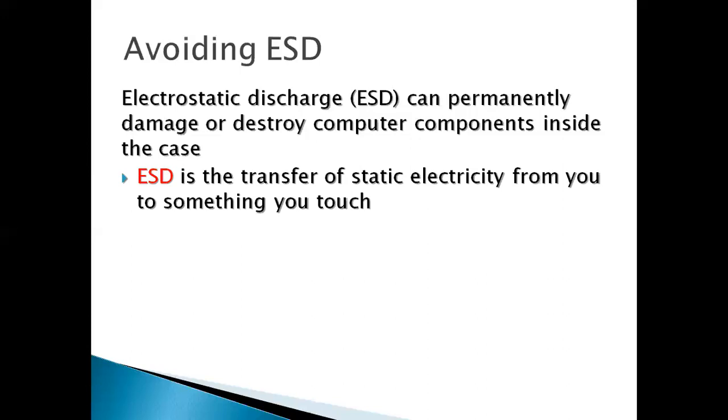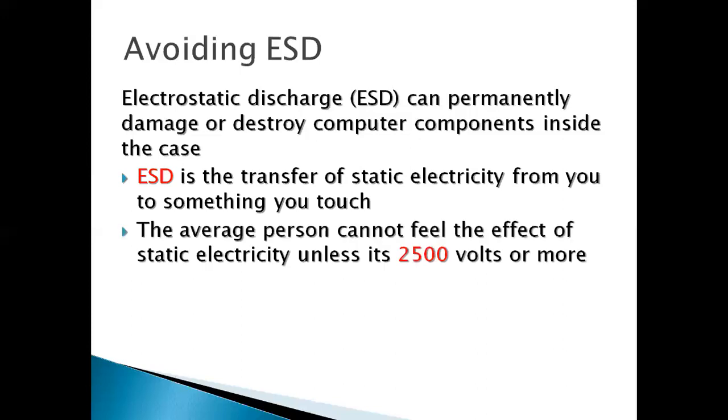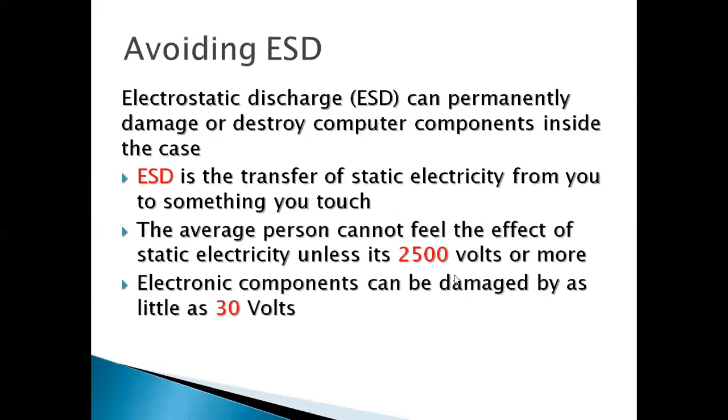If there is a difference in the electric charge of both devices, the average person cannot feel the effect of static electricity unless it's 2500 volts or more. So electronic components can be damaged by as little as 30 volts.